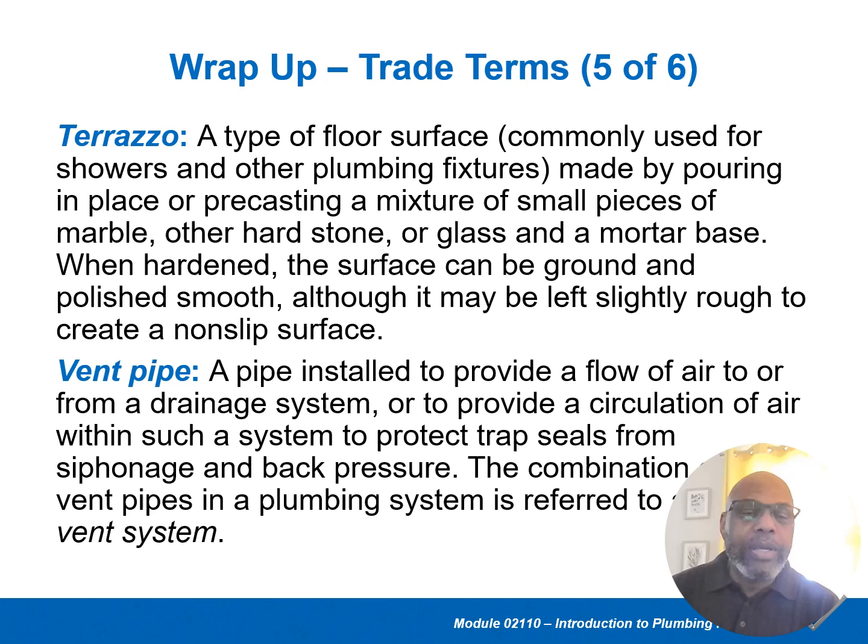It's made by pouring in place a mixture of small pieces of marble, or rocks, stone, colored, could be glass, and it basically is a mortar set. When hardened, the surface can be ground down and polished smooth, although it may be left slightly rough to create a non-slip surface. But usually you find terrazzo floors ground down and polished.